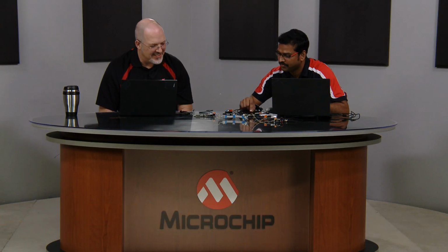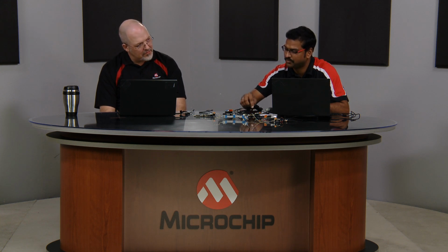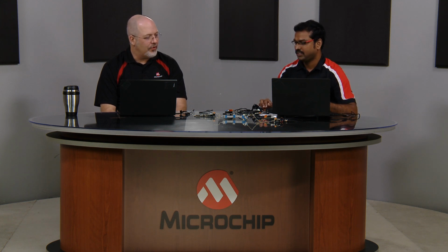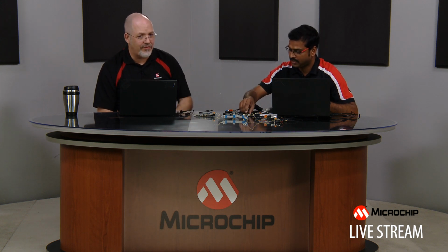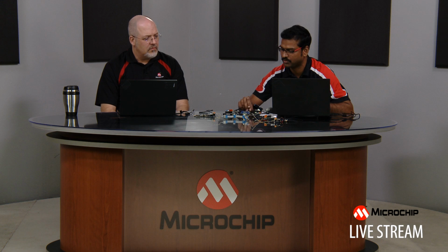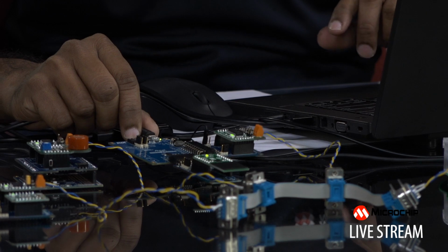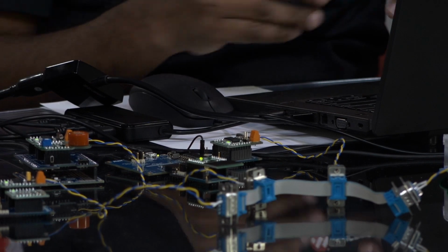Here on the Xplained PRO board, we have 5 volt as well as 3 volt. So you can connect a jumper to 5 volt on the external interface, and it runs with 5 volt. The chip on the board is running at 3 volts, so you have to physically connect it, but there is a facility for 5 volt. This board has 3.3 as well as 5 volt, so you need to have a jumper over here and connect it, and it provides 5 volt. Most of the clicks are 3.3, a few clicks are 5 volt, and a few need both 3.3 and 5. So you have to check the specification for that.